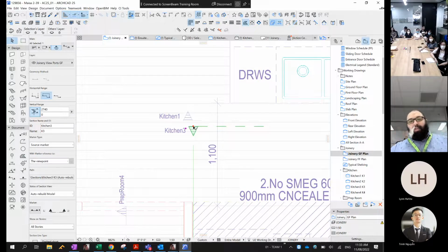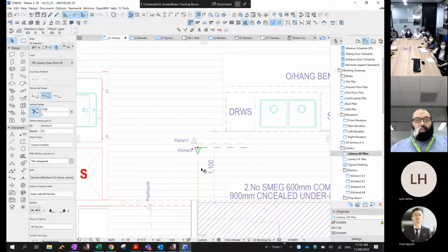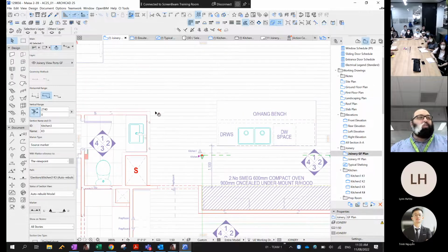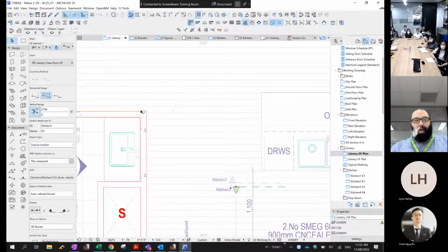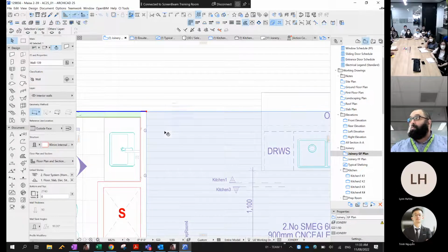So we'll continue on. This is basically an internal elevation marker where you just select it and you can extend it. For these particular masters, where we have two versions of the Urban Edge masters, we have one that has the plaster shown on the internal walls, on the stud wall, and ones without the plaster finish shown on the plans. For the internal elevation markers, we always want to draw them up to the finish.